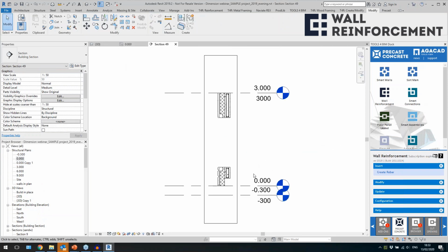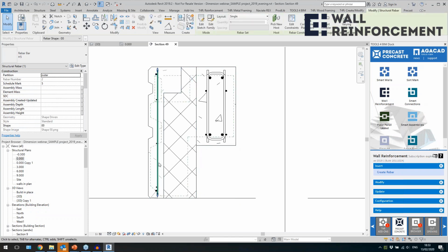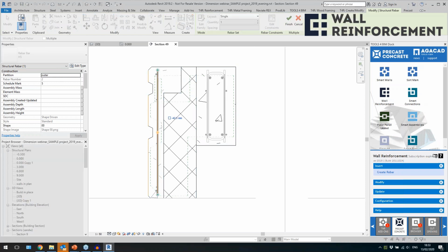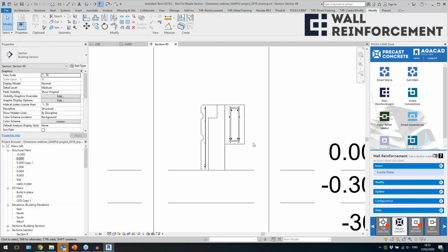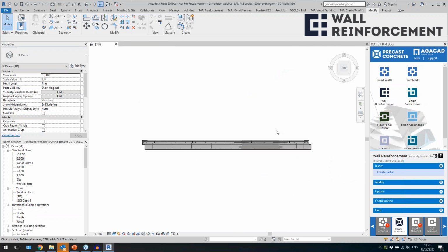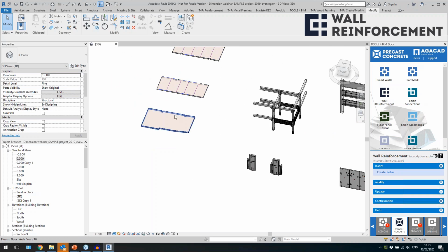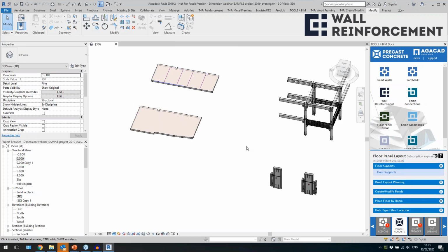And we'll go to the section. And yeah, so it looks like that. So I have this multi-layered wall, right? I have this window with some concrete inside already. Then I have 1 layer over here and 1 layer over here. You see that Revit gives me all of these covers, but we control these covers through the configurations, and then we can constrain them to the faces, and then it sticks really well. It's not losing the position of it, right? So that's one of the ways. I'm not going to create the shop ticket now, because I just want to finish with some other tools.